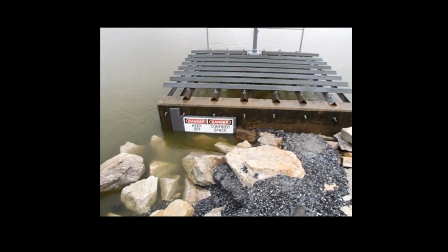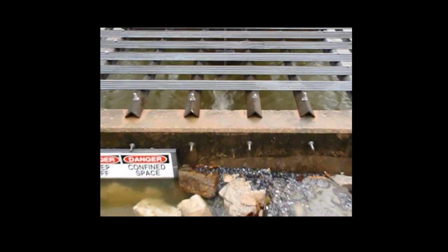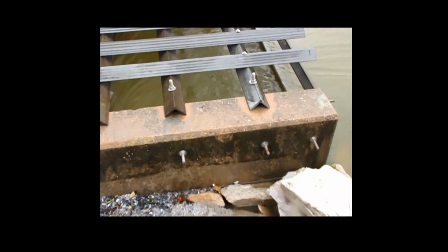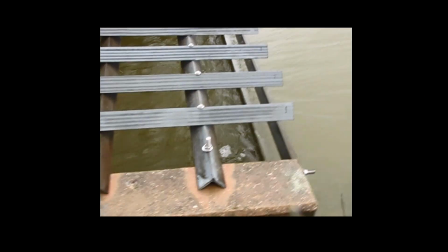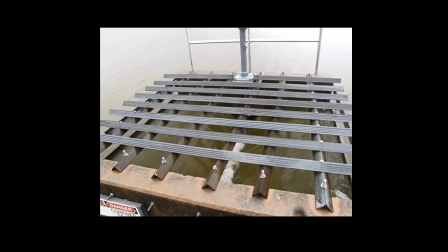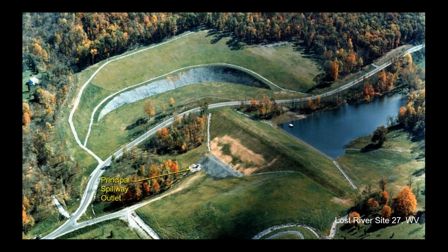And here's a video of one, where you can see what's going on in the top. So if you were to try to look through the top, you can see the two walls on the left and the right. And so the reservoir, as it comes up, flows over the top of the wall, and then it drops down. You can see here, this one's flowing at a pretty decent capacity, and it drops down to the bottom of the structure, and then the water is conveyed through the conduit, through the dam, to the downstream structure. So that gets us to the outlet.